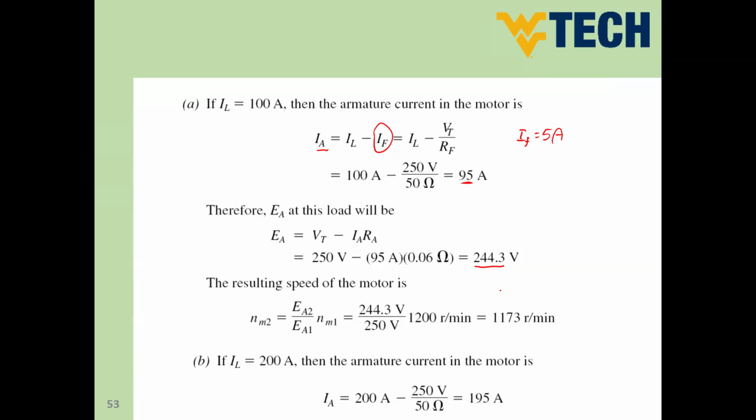So how can we do that? As you can see here, guys, since we calculated the value of the new EMF, you can compare between 2 points, which are the point of our operating condition and the operating condition at no load. And at no load, you can assume that the armature current is 0.